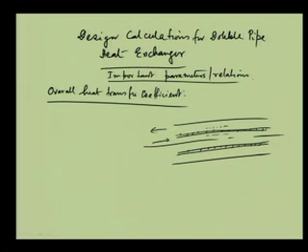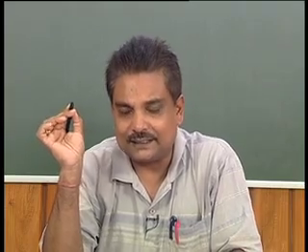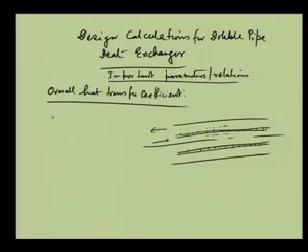And in that case, there are 3 resistances. From the resistance series model we discussed long back, the current is the driving force divided by the total resistances. So the current is the Q dot, and the driving force is the delta T between the 2 fluid streams, divided by the summation of resistances, the total Ri.